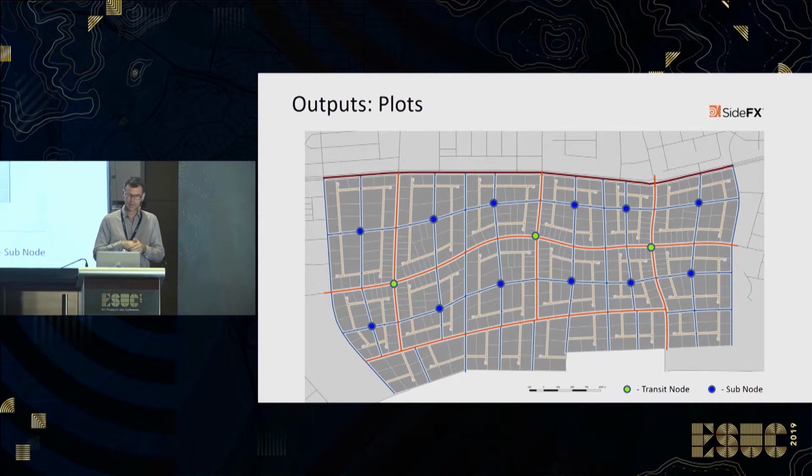Then in the next stage, it subdivides those urban blocks into plots for buildings, and the subdivision is carefully controlled so that the plots that are close to the urban centers are smaller than the ones further away. The way the divisions happen is as much as possible perpendicular to the street, so that when you get buildings, they are facing the street. There are no strange plot shapes.